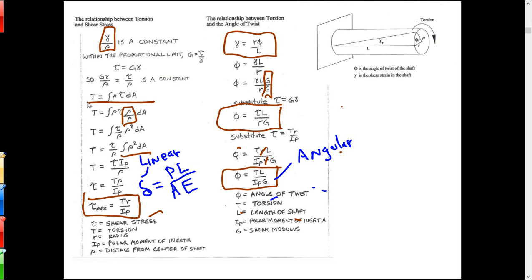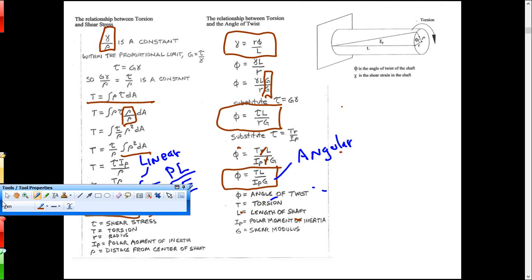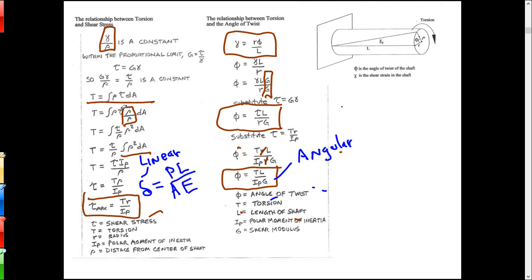Now, underlined in red here, I have the basic torsional relationship. It's the integral of rho tau dA. Now, I can work with this algebraically. What I can do is put a term of rho over rho in there. I've boxed it in red. I'm going to erase it so you can see the tau, but there's that term that I've added to that integral of just rho over rho. Now that's just 1.